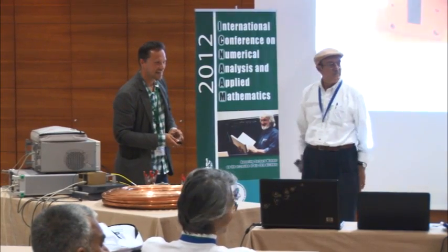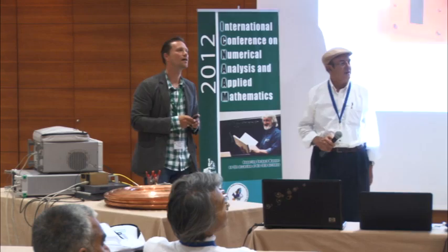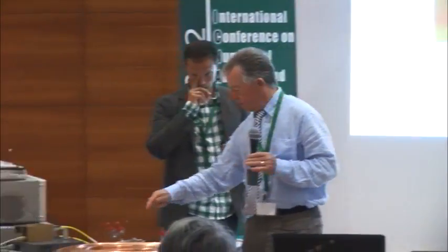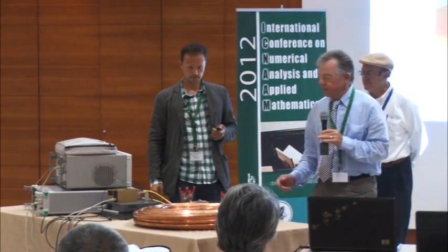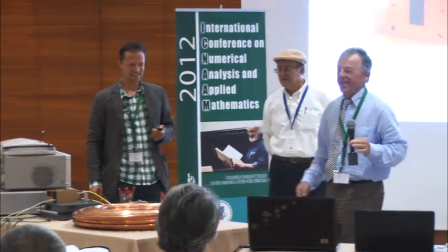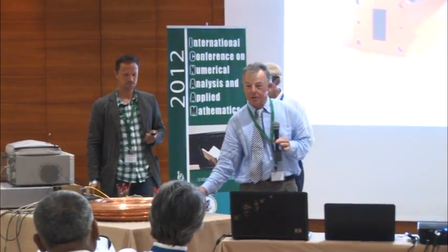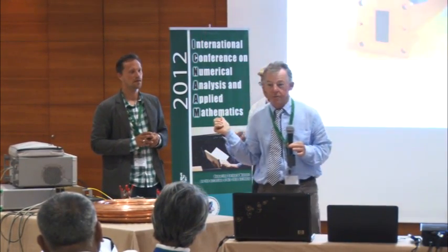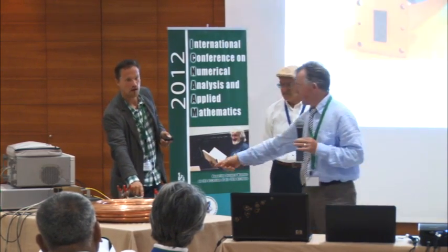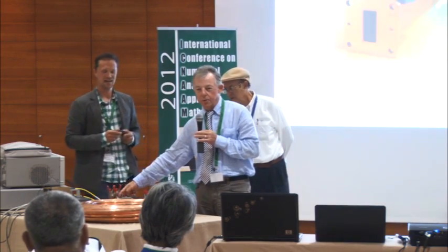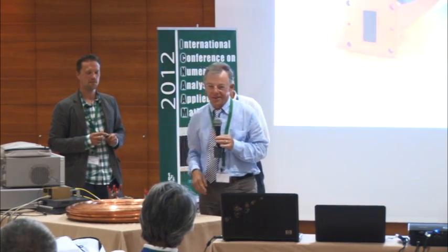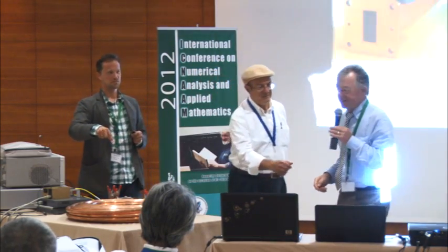It's transmitted to the rectangular waveguide because the rectangular waveguide has the lowest attenuation compared with the cables. And therefore, all the engineers are using the rectangular waveguide. And here you can see it later. However, the rectangular waveguide is very expensive. A meter is about €100, whereas the cable is about $1, and this is very cheap. And this is used for TV transmission to the satellite, this mode he has shown before. Maybe one other comment. For circular mode, they use exactly this adapter from rectangular to circular line to the satellite, 40,000 kilometers up. But we are at the entrance now.